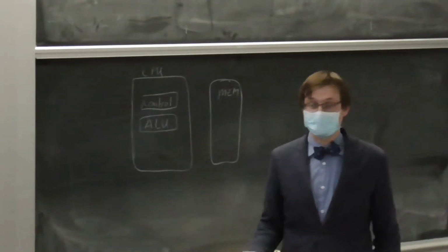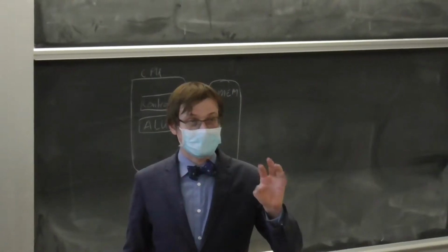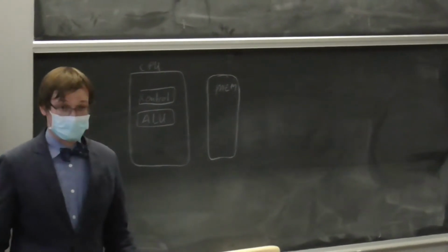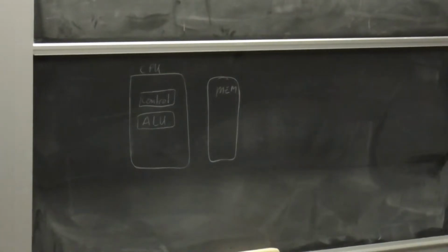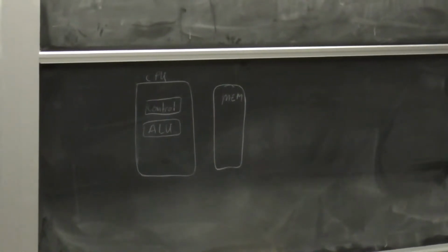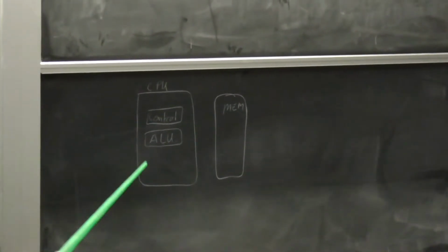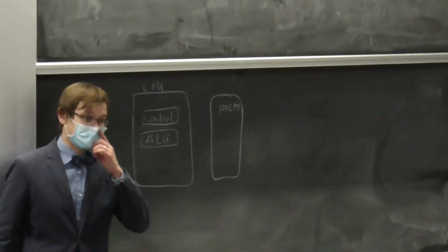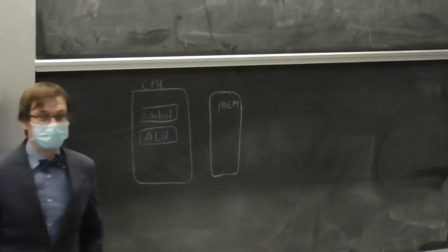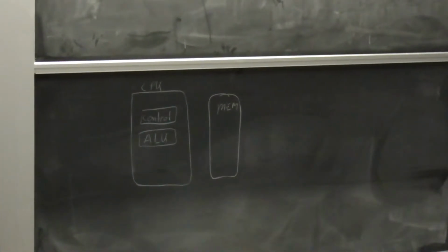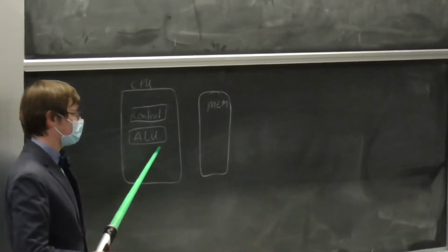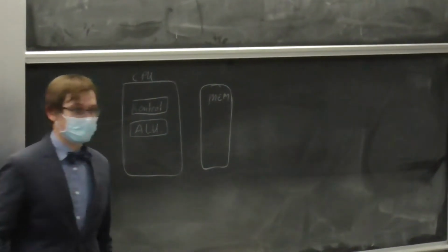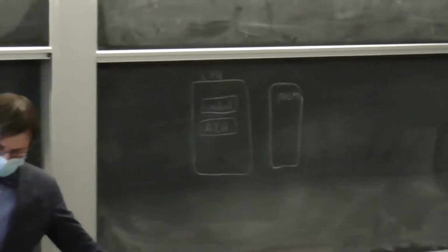The arithmetic logic unit, just to remind ourselves, performs all of those little manipulations that we saw in the previous example. It's arithmetic and logic, right? The memory is stored elsewhere. In our case, we have registers inside of the data path unit. So between the memory and the arithmetic and logic side, that constitutes the data path, right? Because, well, that's the path that data takes. The data itself starts off stored in memory, is loaded into the ALU, is operated on, and then stored back in memory, right? That's the path of the data.